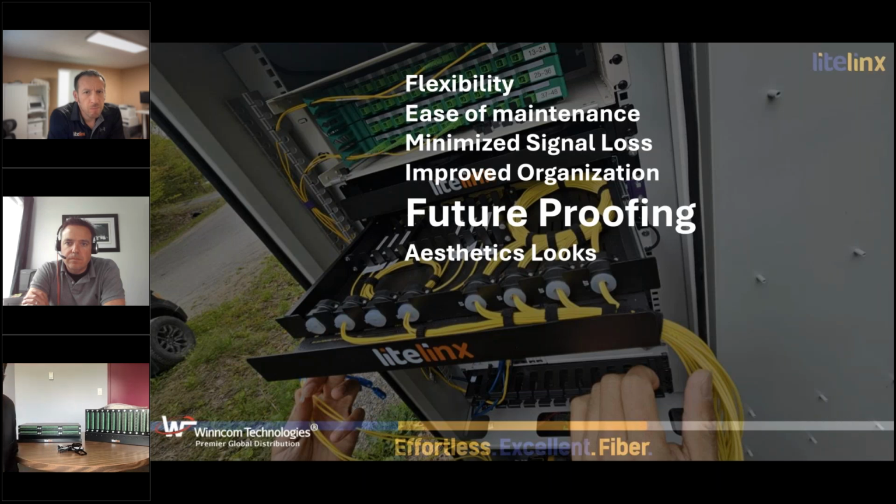And in one of the OLTs, we are also able to leave 1:2 and 1:4 splitter options together, because the solution, which is customized, allows us to do that. So when you talk about future proofing or future spaghetti removals, this is the way we found that is more economical to do it. Add your patch cards, leave the patch card for the future. When you add the electronics, your cabling is already there.